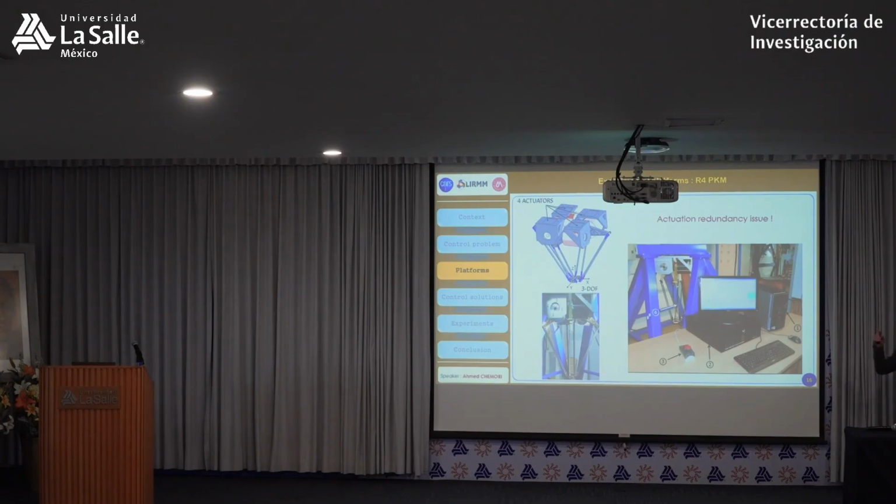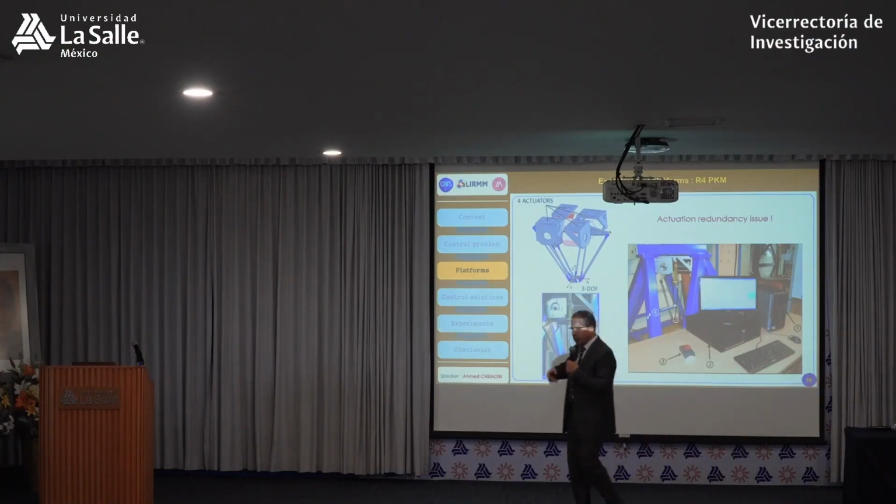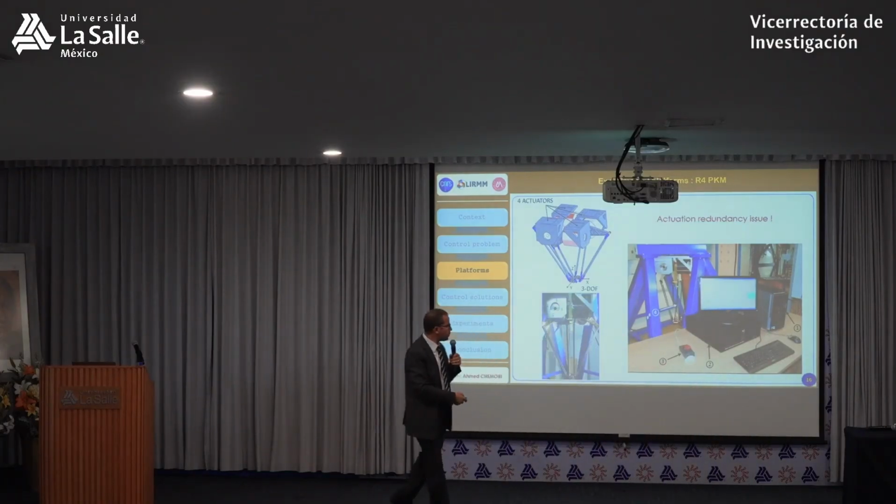The second computer is something specific. It's an industrial computer with a higher computation capacity. So you upload your code here, and it's executed in real time, and it is connected to the robot. So it sends the control actions, and it gets back the measurements from the sensors. In terms of measurement for this robot, we measure just the joint positions. So q1, q2, q3, q4 only. And then from this we can compute the speeds, we can design the controller, and so on.